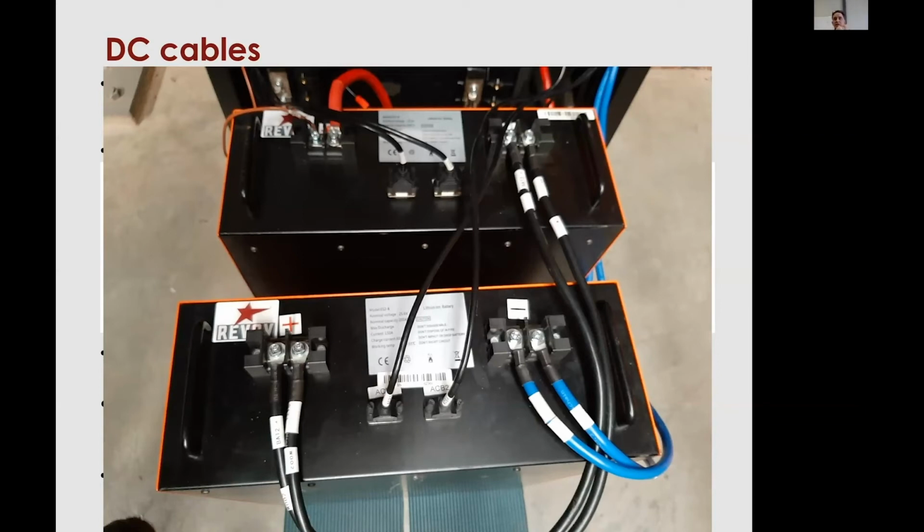What I did not realize is that people were not using these cables as their best guide. If their design was longer than 2.5 meters in terms of the total DC circuit run, in other words, from the negative of the inverter all the way through everything and then back into the positive of the inverter, they weren't doubling up on it. They weren't making sure that this was at least a full system. So I'd like to recommend that people follow this picture or this guidance,